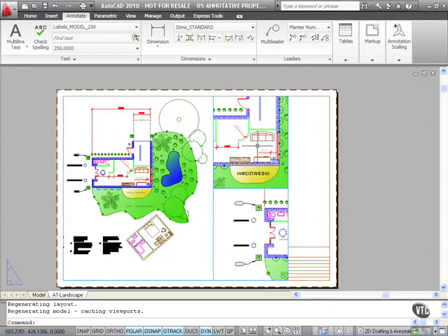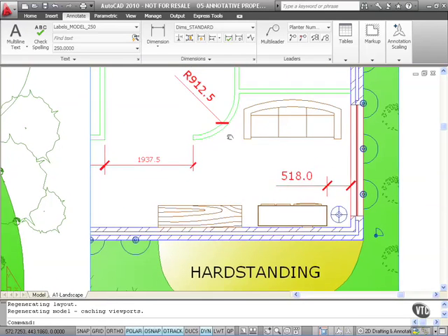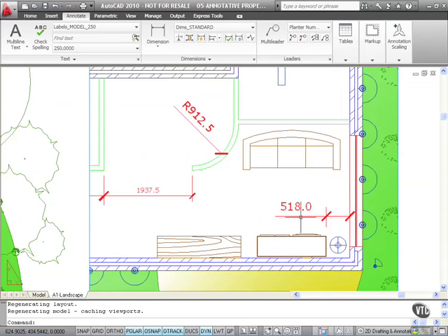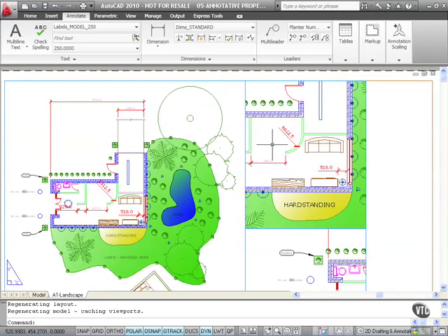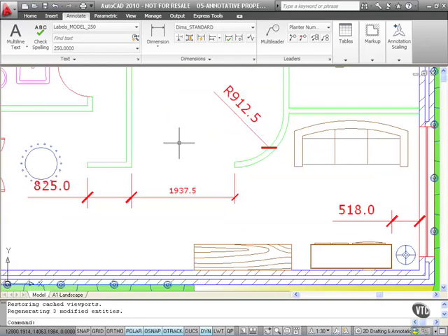In here, again, they're showing the wrong size again. Can you see that? So we need to change this. How do we do it? Well, first of all, we do need to save the drawing at some point. But also we need to do a regen in our model tab. First of all, always do a regen if there's any issues like this. That's the first thing to do. That doesn't do anything either.